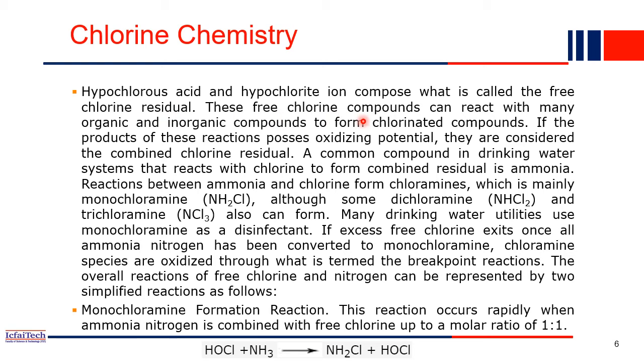This free chlorine can react with organic and inorganic compounds to form chlorinated compounds, right? In the water, organic and inorganic material will be there, and viruses and bacteria will be there. So it will react with the organic and inorganic compounds and form chlorinated compounds. If the products of this reaction have oxidation potential, they are considered chlorine residuals.